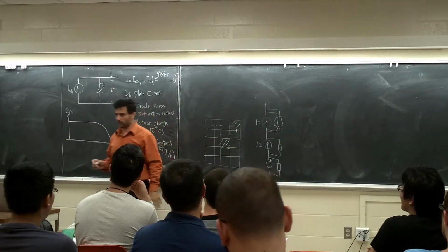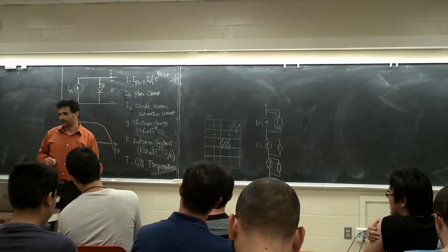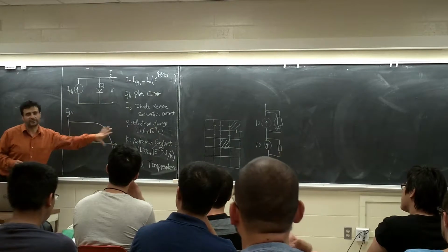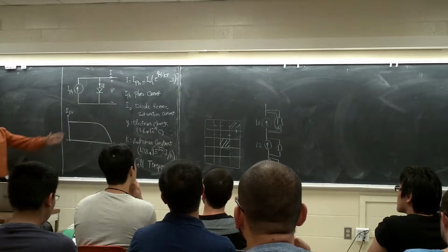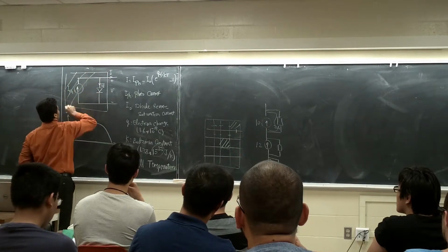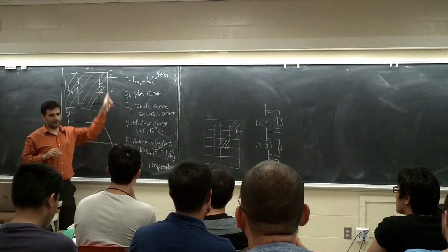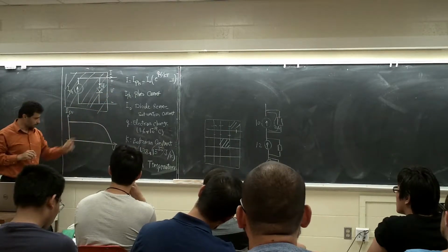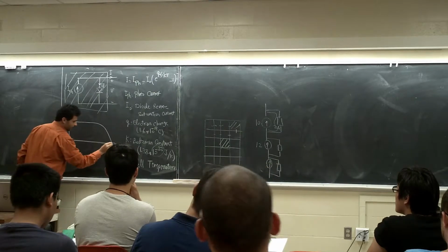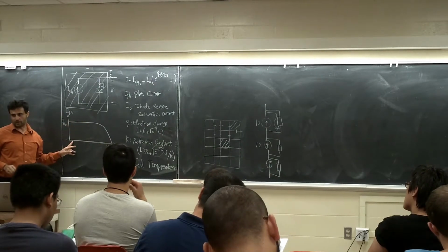Now let's talk a little bit more about the characteristics of these solar cells and what maximum power point tracking is, and we'll figure out what I'm saying a little bit more. This is the characteristic of the cell, right? This is my cell. I don't care what's happening inside this one. I'm looking at this V-I characteristic here, right? They call this one I short circuit. This one they call V open circuit. It's clear. Why short circuit? Because voltage is 0, right?